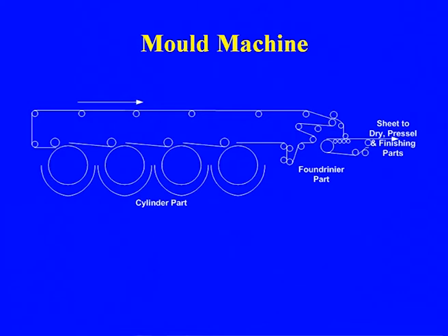So here the pulp slurry is there, and this will be the transfer of the pulp sheet, that is the web paper, on the felt, continuously. If you want to increase, in the two molds there will be different types of pulp, so 2 layers of the pulp will be made, because one layer here, again another layer, so it may be 4 to 6 cylinders that may be there, and finally the board or the paper will go for the drying purpose.